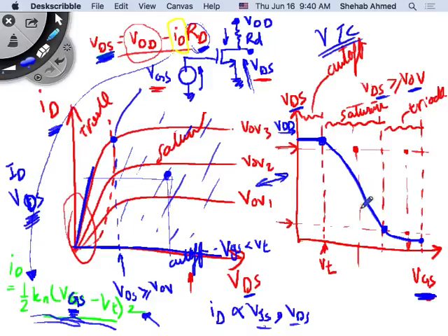If you put a small signal here, you want to maximize the value of the output signal, right? How do you maximize? You take the place where you have the highest slope, right? And the place where the highest slope is definitely around the middle here, right? So the slope is going to be the tangent to this line. Looks pretty linear, but it's really not linear. If you take a point somewhere here, this will be your DC operating point. You can call this your Q or DC operating point or quiescent point.